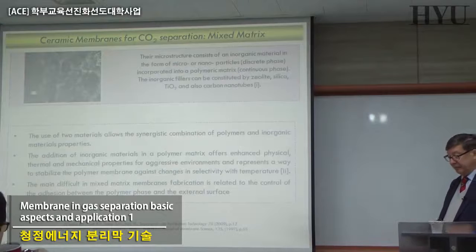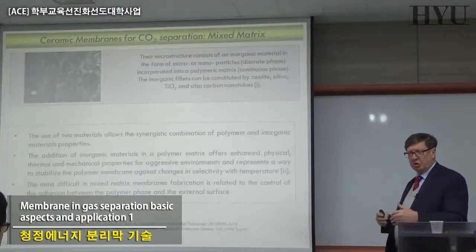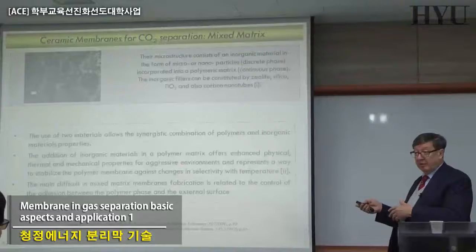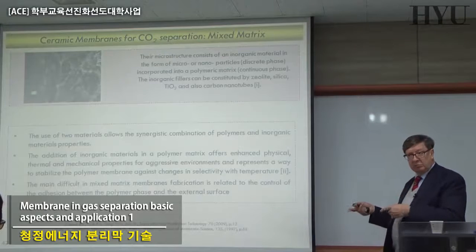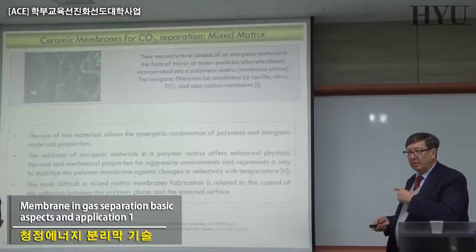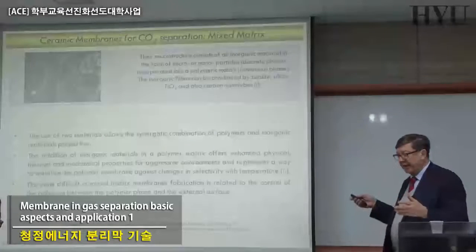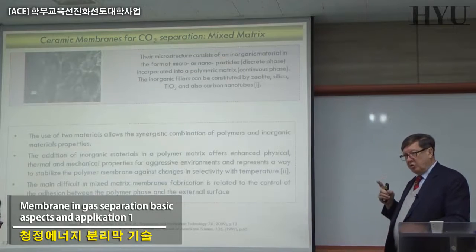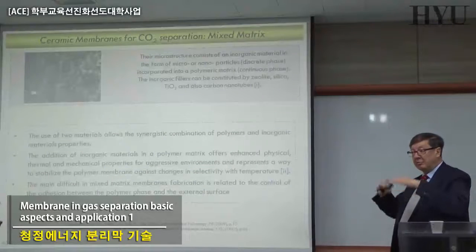all traditional ion exchange columns or all traditional adsorption columns, in which a lot of material is still utilized today, are slowly disappearing when you can redesign the chemistry of the same material, which is quite effective sometimes, in a membrane configuration. So the properties of absorption, desorption, and selective permeation, etc., are just the same, nothing changed. What is changing is the engineering of the system, having an interface that is controlling the mass transfer.